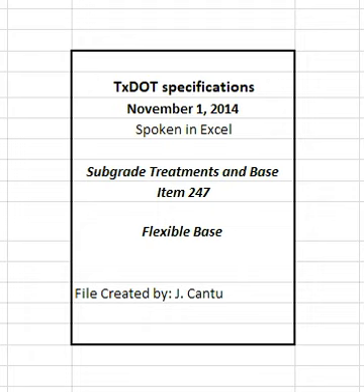Maintain the shape of the course. Control dust by sprinkling, as directed. Correct or replace segregated areas as directed, at no additional expense to the department. Place successive base courses and finish courses using the same construction methods required for the first course.